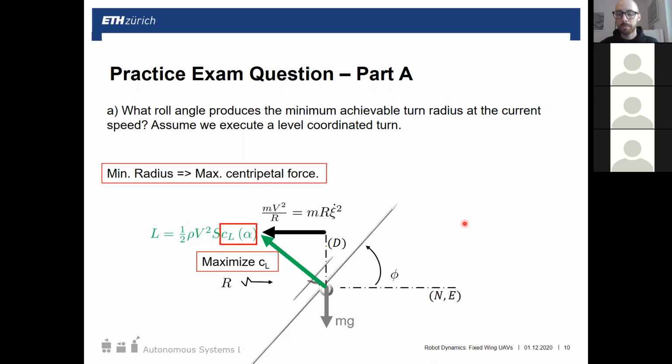Yeah, actually, my question was about the direction, right? So I know that it has to be perpendicular to VA, right? Mm-hmm. And VA is the velocity that the airplane has with respect to what we call wind or the air, right? Sure. And if I have wind, we saw in the slides we change VA in the body frame because we represent VA in the I frame, and then we add the wind component.